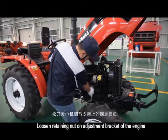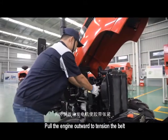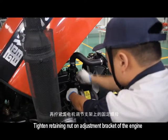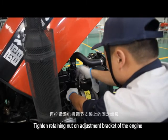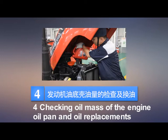Loosen retaining nut on adjustment bracket of the engine. Pull the engine outward to tension the belt. Tighten retaining nut on adjustment bracket of the engine. 4. Checking oil level of the engine oil pan and oil replacements.